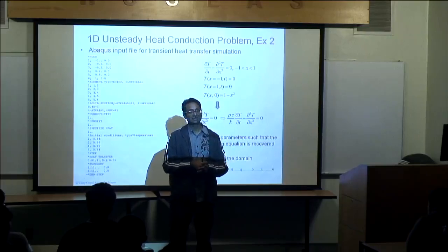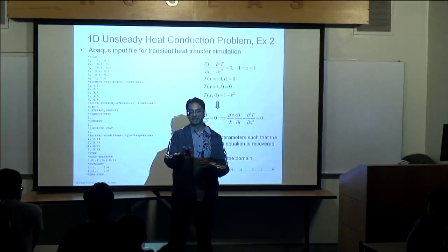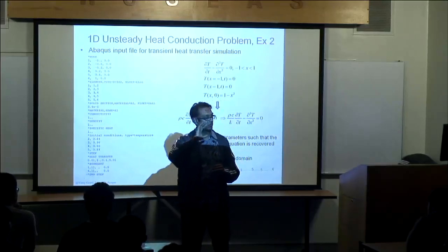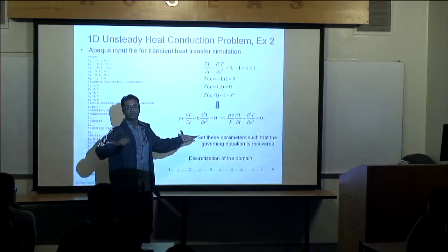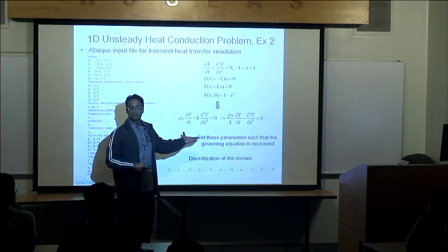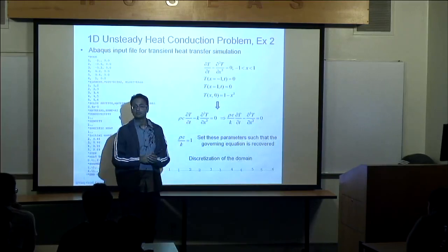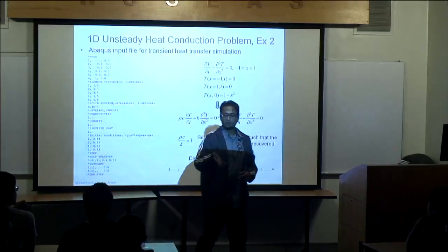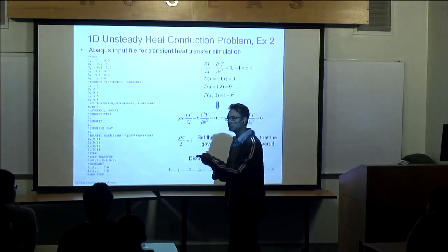Are you tracking? I don't know if you follow me. Some of you may not have noticed this, but I can actually use Abaqus to solve problems that have nothing to do with heat transfer. I can select another problem, and maybe rho c and k for the problem I'm working on have nothing to do with heat transfer, but you can specify what rho c and k are, so it becomes the problem that you're interested in. Do you follow? Okay, I'm teaching you this because I've done something similar. I've tricked Abaqus to solve a non-heat transfer problem. Okay, there's a question right here.